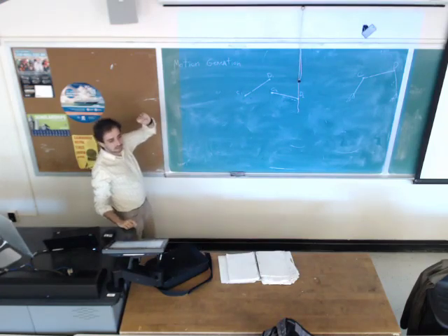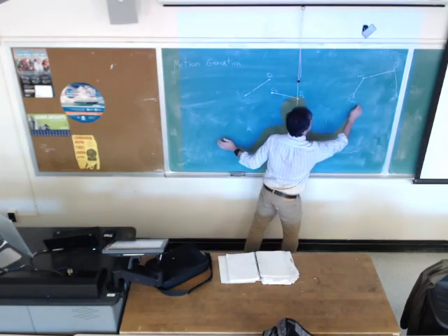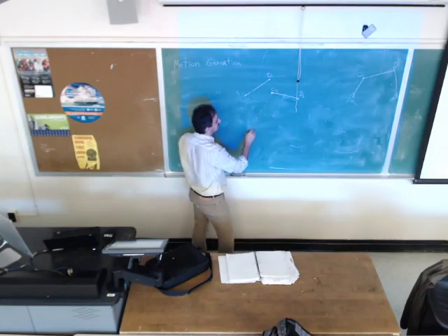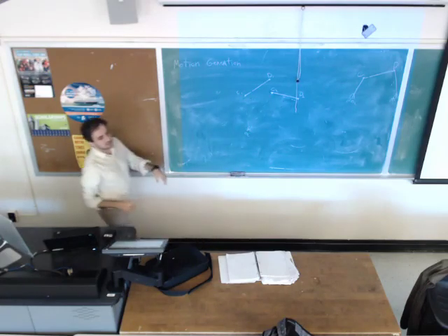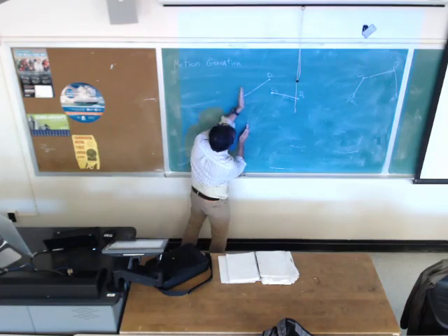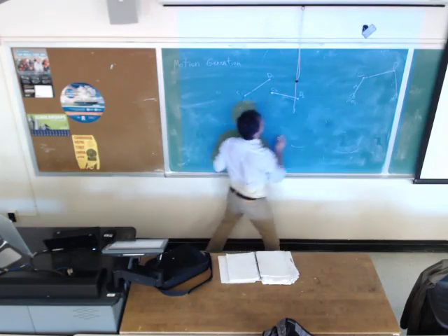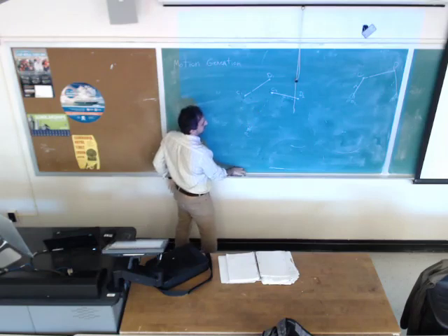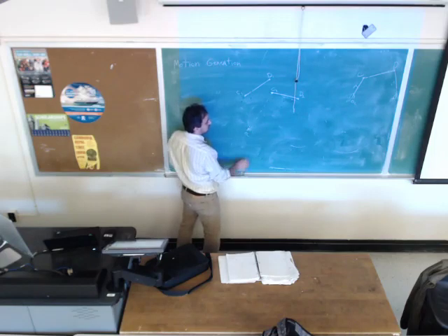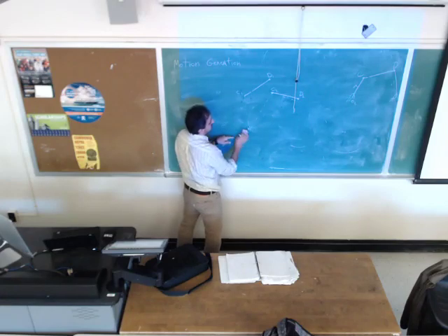Make sense? What we are going to do. So joint O2, wherever it is, has the same distance from point C1 and C2. True? Because when I fix this and when the mechanism is moving from this position to this position, the length of the link is not going to change. It's going to be A, whatever it is. So it tells me point O2 should have the same distance from C1 and C2.